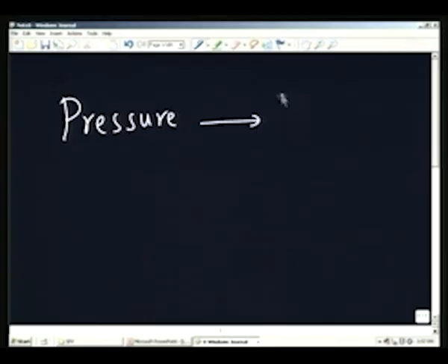But the formula helps us in identifying the fact that there is a direct linear relationship between the displacement and the pressure. Therefore, in this particular transducer, we can say that pressure is converted to a displacement, and in fact this is called transducer action.